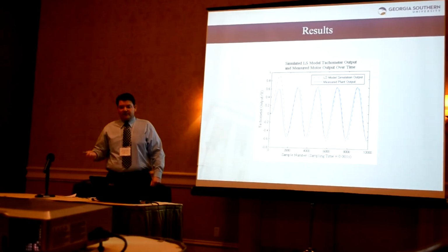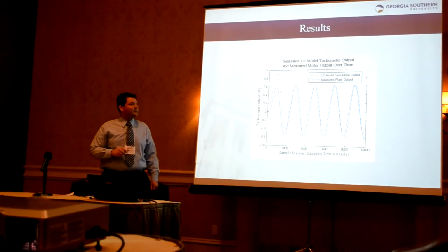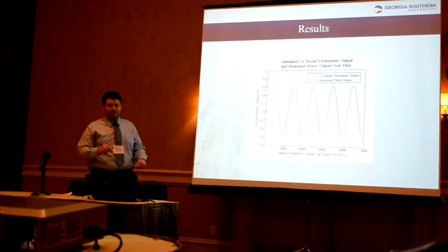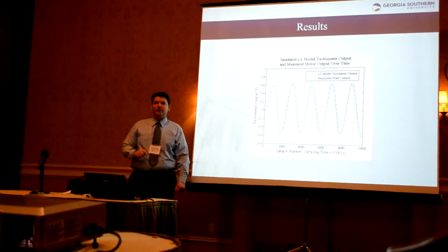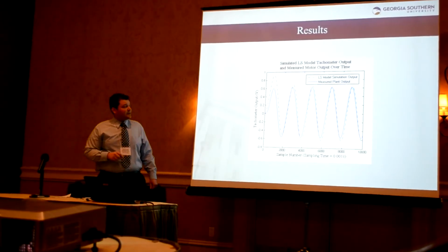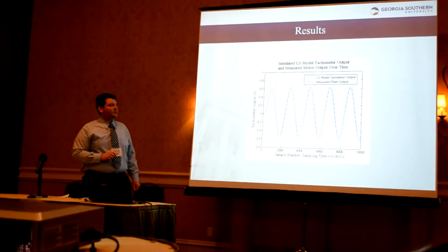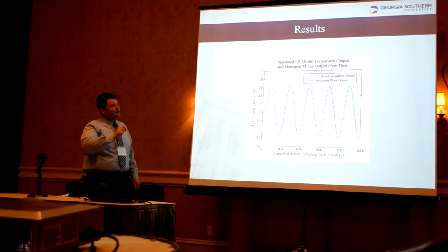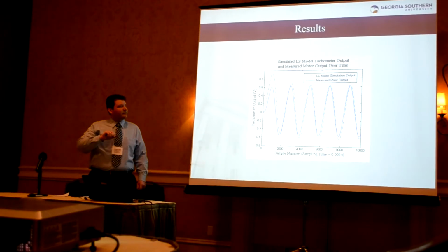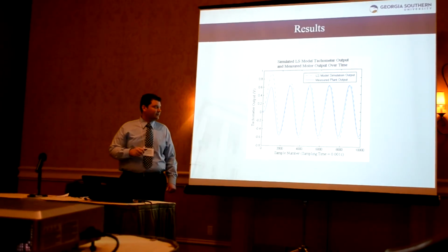We actually simulated the system model we developed using the least squares algorithm, and here you can see a plot of the simulated system response compared with the actual system response, shown by the solid line. These are responses to the 0.5 Hertz, 3 volts peak to peak sine wave. After the 2-second mark, the fit is good. In the first second or so, you can see a problem with the magnitude of the simulation's response, and this is caused by a couple of things.